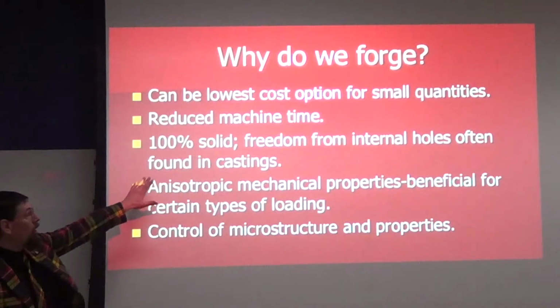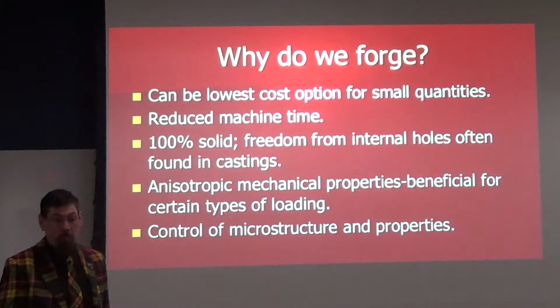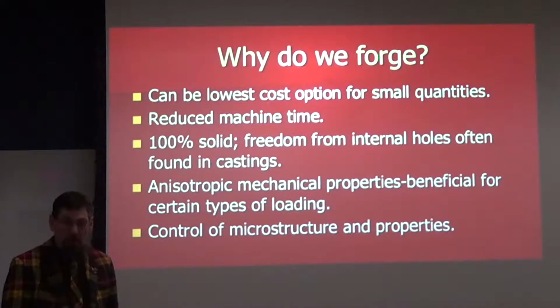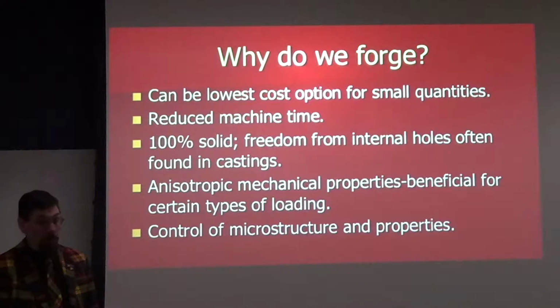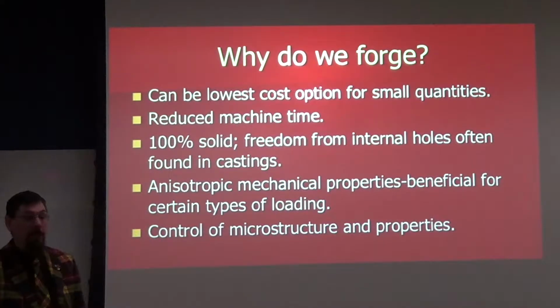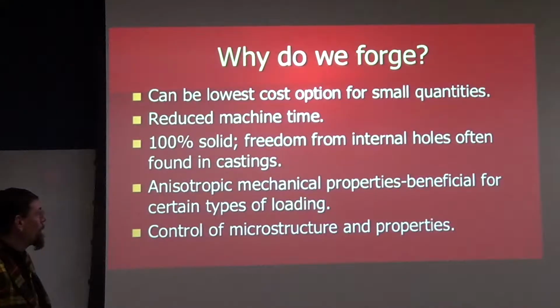So we also don't want those little holes in castings that are there not only because of repair work, but because they can be initiation sites for failure in service. And so a properly executed forging won't have those. Now, I'm going to say that if you don't do forging right, you can have those holes remaining, and that's a problem just as it would be if it were in a casting.